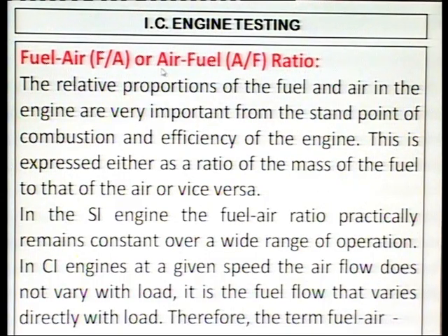Fuel air or air fuel ratio. The relative proportion of the fuel and the air in the engine is very important from the standpoint of combustion and efficiency of the engine. This is expressed either as a ratio of the mass of the fuel to that of the air or vice versa. In the SI engine, the fuel air ratio practically remains constant over a wide range of operation.